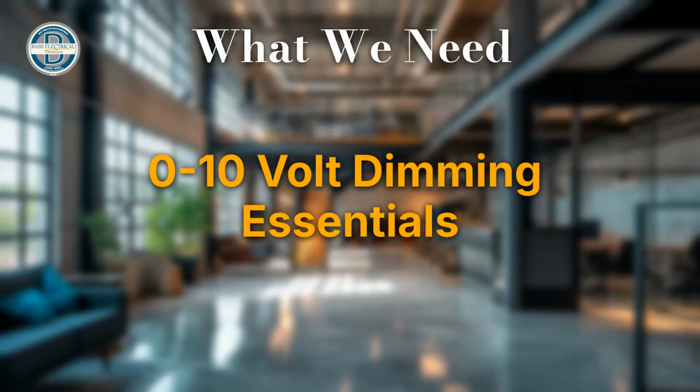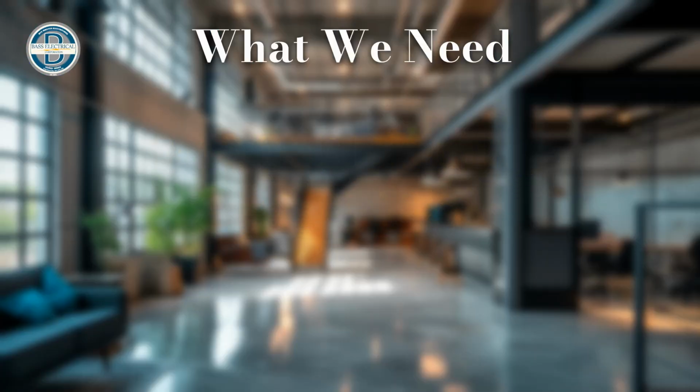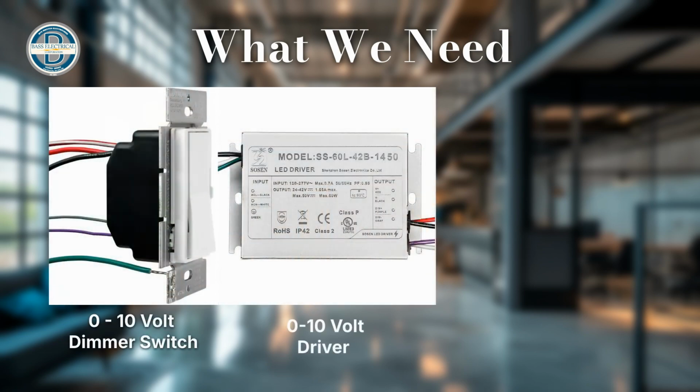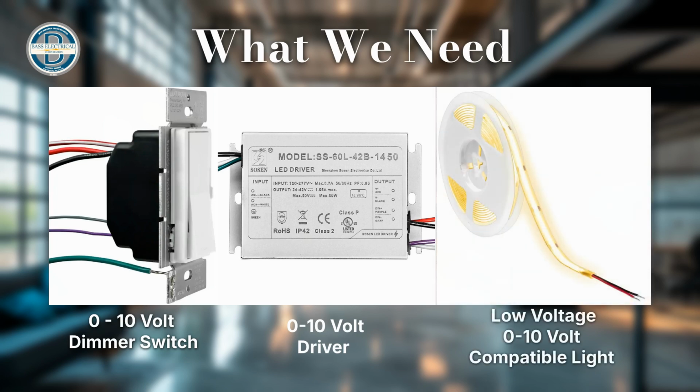For a 0 to 10 volt dimming circuit, you'll need a 0 to 10 volt dimmer switch, a compatible driver for low voltage fixtures, or a 0 to 10 volt fixture that doesn't require a separate driver, along with control wiring. Only a 0 to 10 volt dimmer will work with this system.